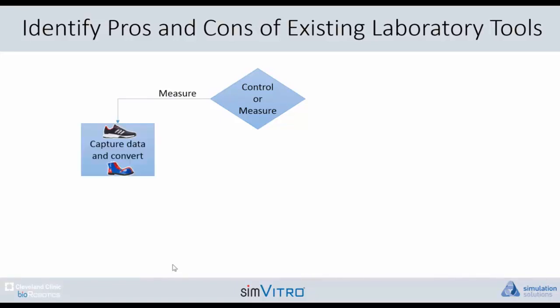And so if you're just measuring and your laboratory tools, software, motion capture, whatever, give you the data in XYZ roll pitch yaw, don't publish it in that reference frame. Please convert it, and we've given you some tools to convert it through rotation matrices to the reference frame that you care about. And that's easy.